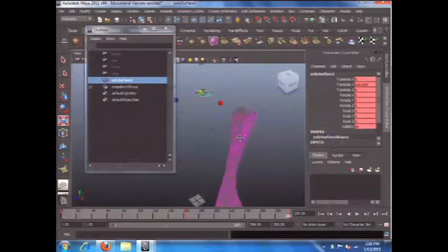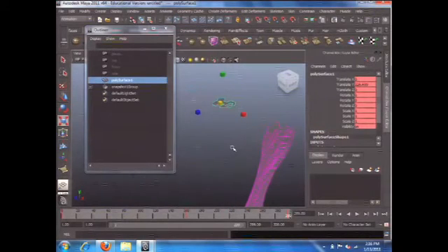And at the top, I want to rotate that a little bit. Use S to keyframe. Just keep in mind, when you rotate, you only want to rotate one axis, along the y-axis, because I do want to have all the floor plans be horizontal. So don't rotate x and z. Here you can see the values.